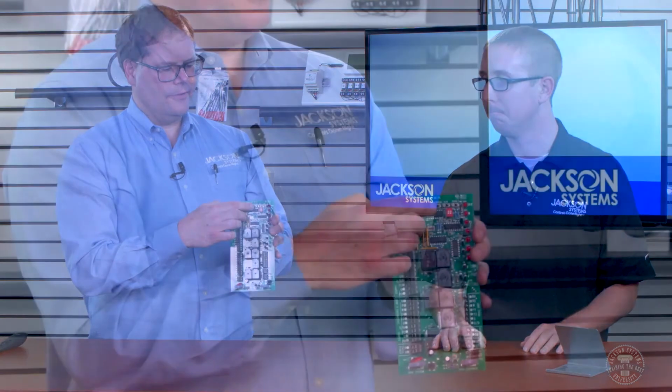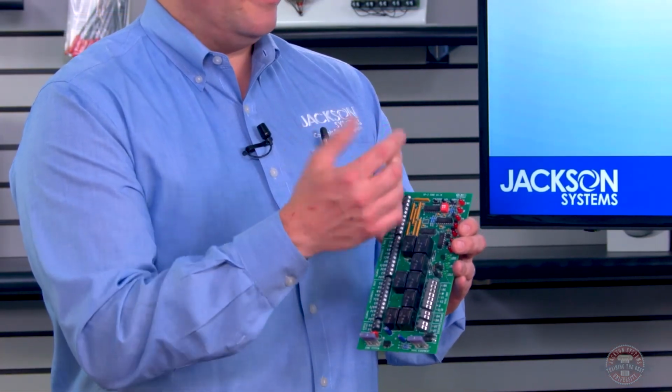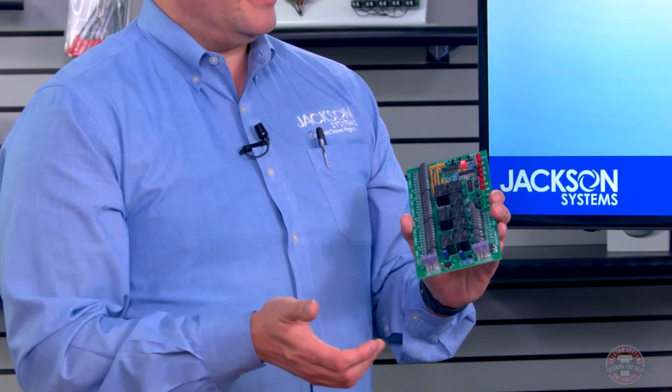So on this panel, if you were doing dual fuel, you would set up the thermostats as a normal heat pump thermostat, not dual fuel, just regular normal heat pump. And then on this particular panel, there's a little switch right up here at the top that says conventional or fossil. So you would throw that if you're doing the dual fuel. Right. And then you'd want to make sure you got the outdoor thermostat as well.